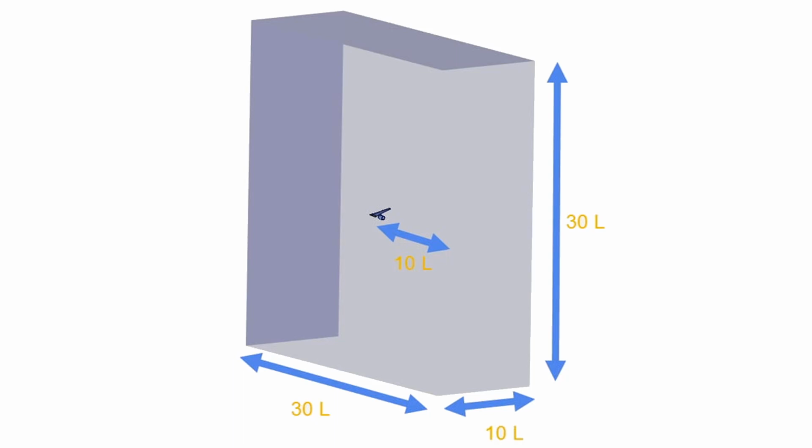Remember that there is no hard rule regarding the dimensions. You just have to ensure that the boundaries of the domain are far away from the geometry. This is necessary to ensure that the flow near the wing won't be affected by the conditions at the boundaries. Keep in mind that the bigger the enclosure, the better. However, a big enclosure will also increase the mesh cell count.